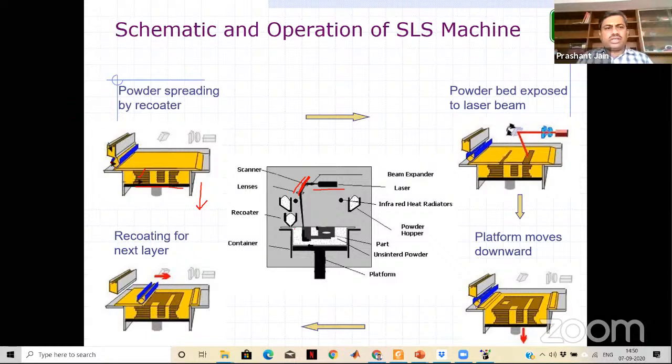So with 40 to 60 micron, this layer has been sprayed on this. You can see this top layer, 40 to 60 micron, and then we have here again this powder is deposited. Right now, the layer is formed. Now the laser light is coming only to the selected area. So what we discussed so far is that the powder is already heated to just 4-5 degrees centigrade below the melting temperature. Now this 4-5 degrees centigrade temperature rise comes from this, right?